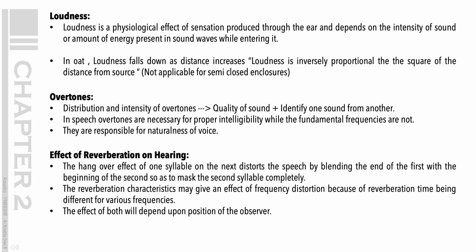Effect of reverberation on hearing. The hangover effect of one syllable on the next distorts the speech by blending the end of the first with the beginning of the second so as to mask the second syllable completely. The reverberation characteristics may give an effect of frequency distortion because the reverberation time is different for various frequencies.